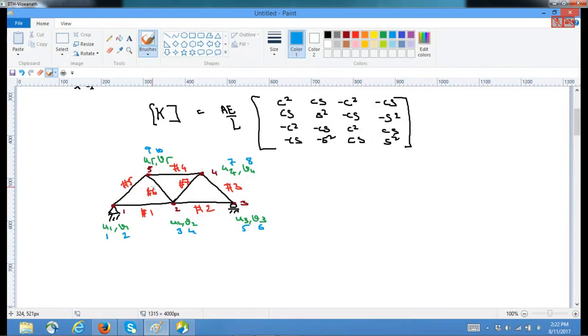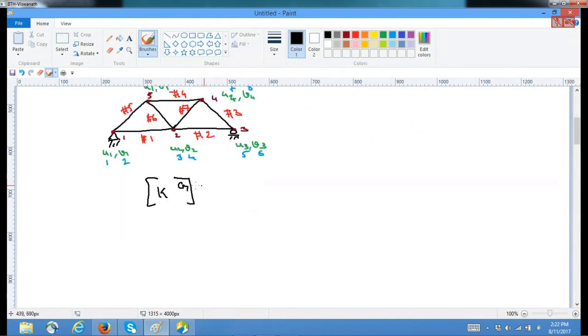So that means our global stiffness matrix Kg was a 10 by 10 matrix because we had 10 degrees of freedom. And our total degrees of freedom vector D is singular because boundary conditions have not been given, and the boundary conditions have to make the structure stable. That is, they should arrest all the corresponding rigid body displacements. When those are arrested, then only you can invert the K matrix.